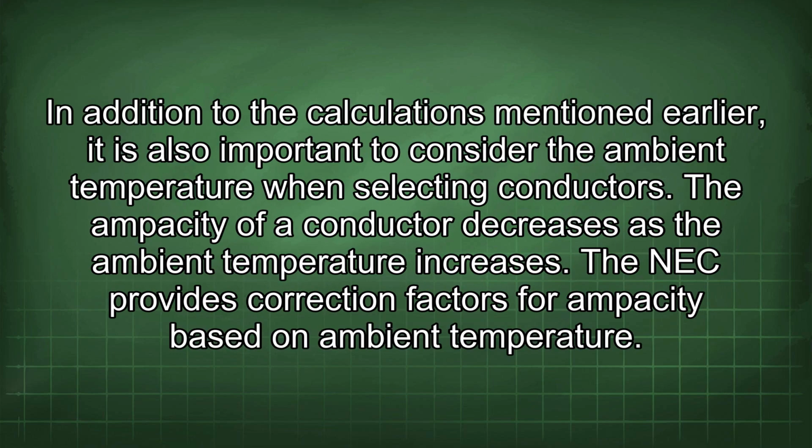In addition to the calculations mentioned earlier, it is also important to consider the ambient temperature when selecting conductors. The ampacity of a conductor decreases as the ambient temperature increases. The NEC provides correction factors for ampacity based on ambient temperature.